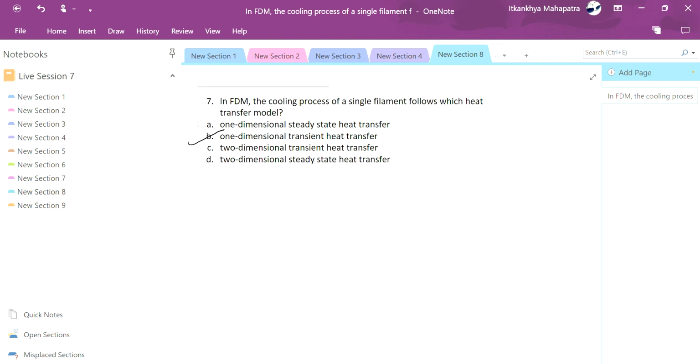Like a single deposition is considered as a one-dimensional block. Now, the head moves at a constant speed of v along the x-axis while extruding, and this conduction heat transfer can also be considered in the form of convection, because the mass of the foundation is much higher than the filament, and the conduction at the interface would not change with the temperature. So here it is known as the one-dimensional heat transfer model.